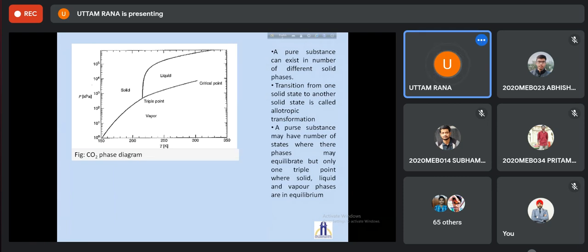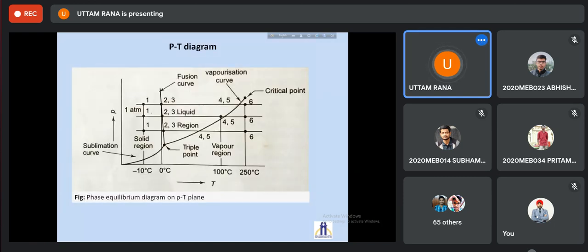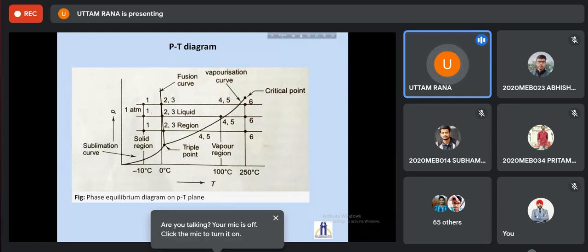For example, if you look into this particular phase change diagram, you can see when the substance is in state 1, you have to specify both temperature and pressure to specify its state. If you go into the superheated region or the subcooled liquid region, you need to specify both pressure and temperature, or any two independent properties, to specify the state. If you go to the two-phase region, that is phase transformation, you have only one independent parameter, but still you have to define two properties.